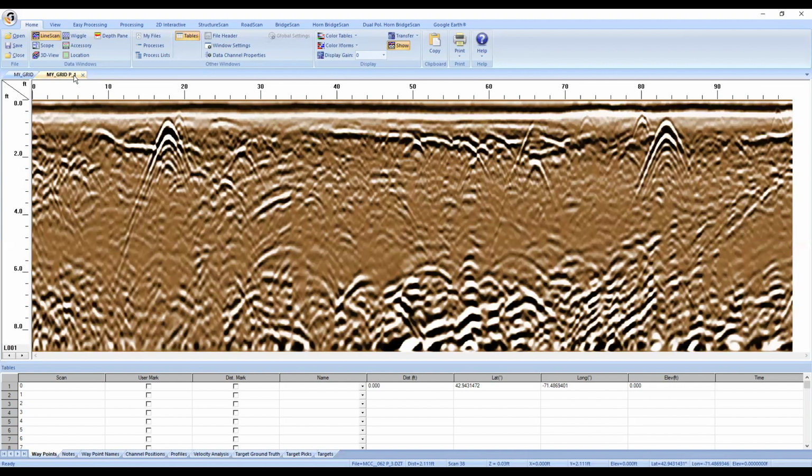But just to maybe note that down, when you assemble grids using 3D batch of files and you have DZT and DZX files, which is what you get by default from our current generation systems, you will get this two grid setup at the end where you can view the raw one and the pre-processed one. For the other assembly function we'll talk about later, 3D file assembly, we will only get the raw version of the grid. We will not see the pre-processed version.